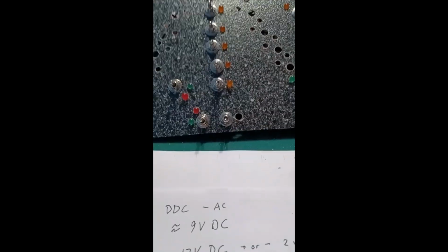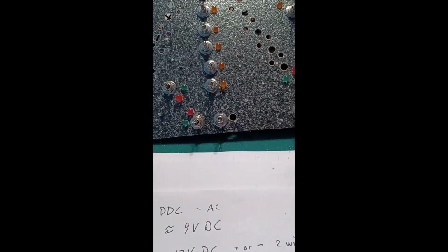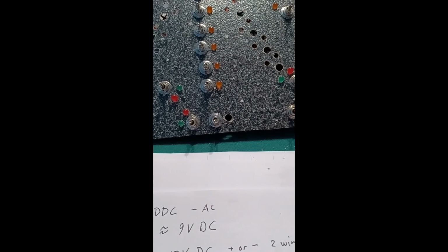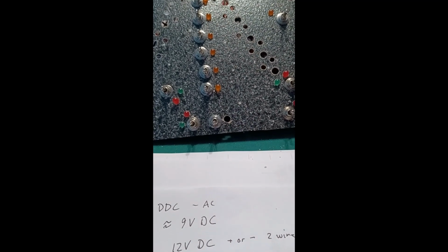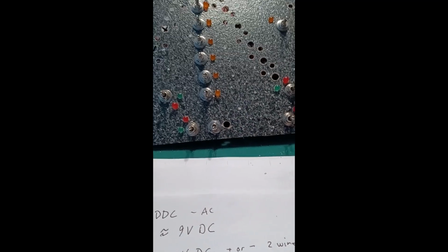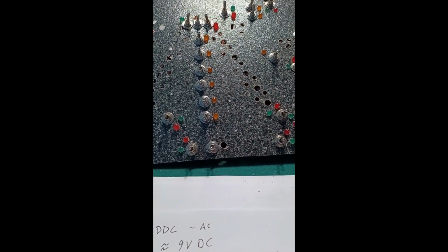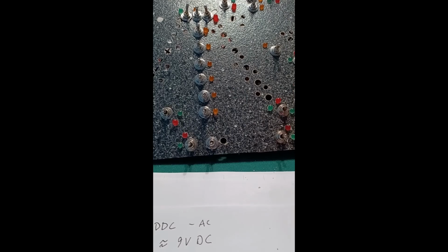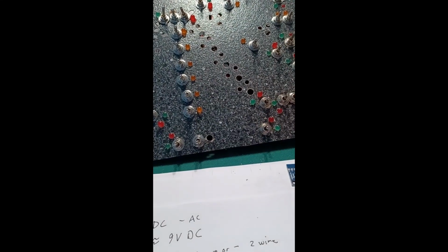Now, I mentioned that the turnouts are all momentary, and it's not just the Katos, but the rest of the turnouts. So you never send a consistent signal or consistent voltage to the turnouts because they'll burn up the motors. So you need these momentary switches to flip the turnouts.